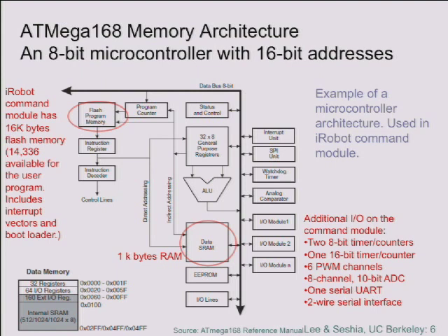So what happens if you accidentally overwrite the program counter by writing to the memory address that refers to the program counter? Well, you'll start executing whatever is in memory at the address that you just put into the program counter, whether it's a program or not. Okay? That makes debugging fun.